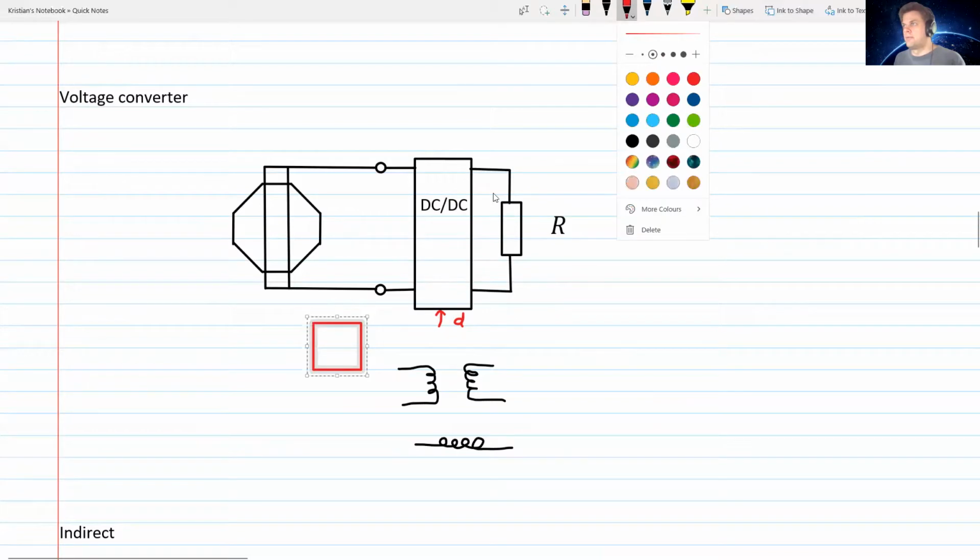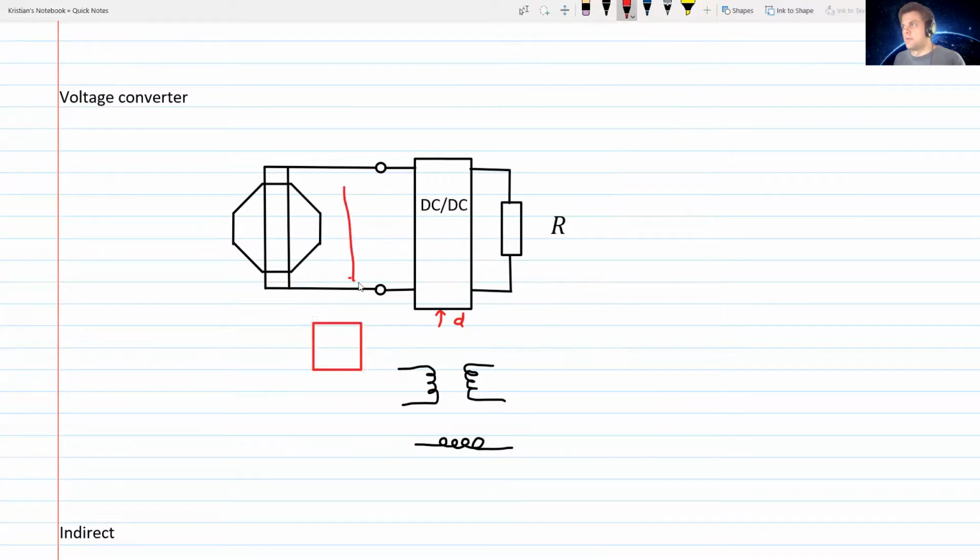measure the voltage and the current of the photovoltaic cell. With these measurements, we can insert them into a controller. This controller can then decide on which way to change the voltage applied to the photovoltaic cell to keep it operating at its maximum power output.